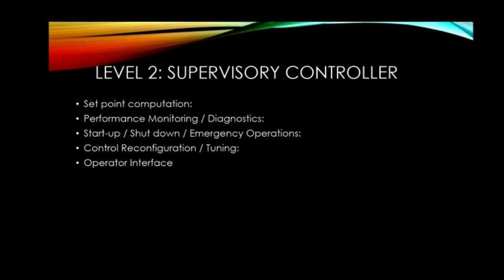Structural or parametric redesign of control loops are carried out, either in response to operator commands or in response to diagnostic events such as detected failure modes. Control reconfigurations may also be necessary to accommodate variation of feedback or energy input, for example gas-fired to oil-fired. Operator interface. Graphical interfaces for supervisory operators are provided, for manual supervision and intervention.